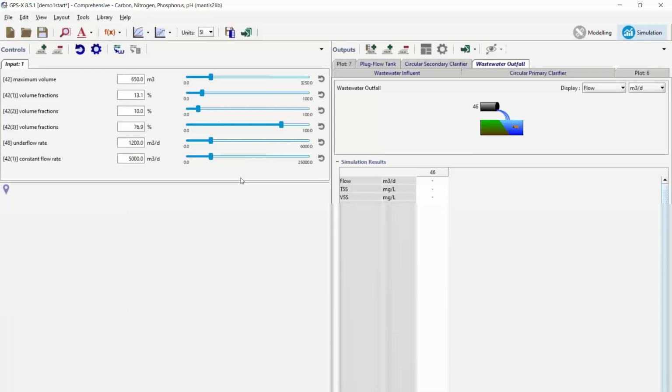Now, the important thing is, just like the other influent distributions, you need to come back to this menu and take a look. Previously, I showed you the menu that had influent fractions and recycle fractions. Now we also have this influent number 2 fractions. This is where you would specify where to put this carbon dosage. So in an A2O system, you would want it to be like this because you would want it to go into the middle one, which is the anoxic zone, which is where the denitrification would be happening. Don't think our example was very carbon limited though, so we were doing pretty good.